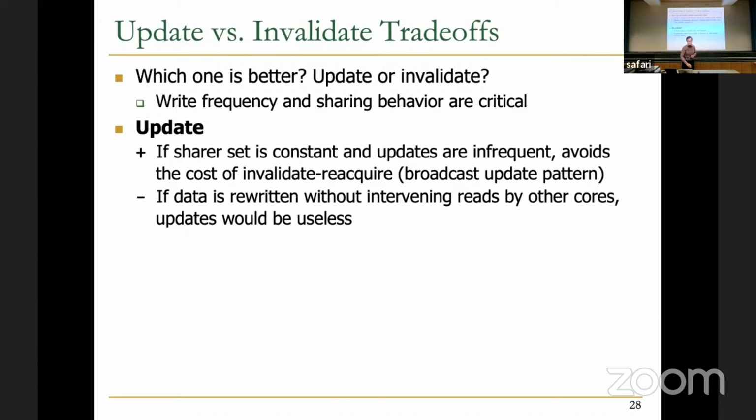So in general, modern machines don't use update protocols because of this reason. Because if you actually send the data to some other cache and then they update it, usually that's a lot of overhead, first of all. That's a lot of bandwidth overhead on the shared bus. And also the other processor may not use it unless you have some other information like sharing information.